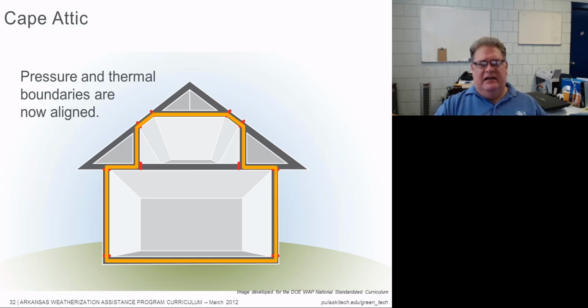Here's another look at that, and this is what we were talking about earlier. This is that attic, or the sidewall. I'm sorry, the knee wall that we were talking about. The goal here is to air seal at the top plate back over the exterior wall, at the floor that runs underneath this bonus room right here. Call it an upstairs bedroom, bonus room, story and a half, whatever you want.